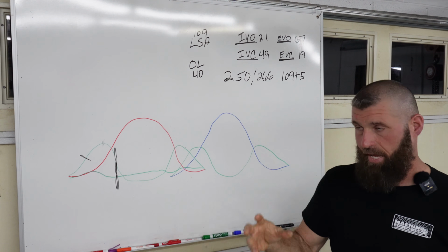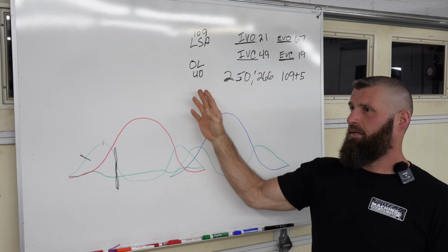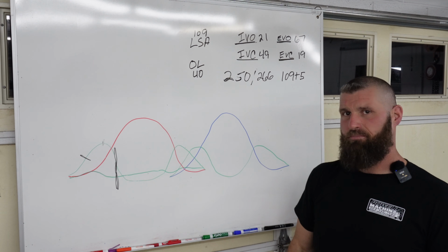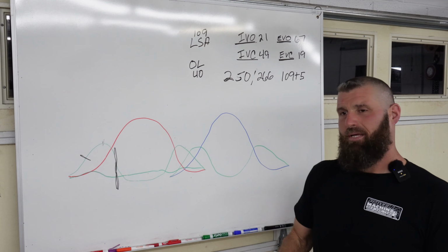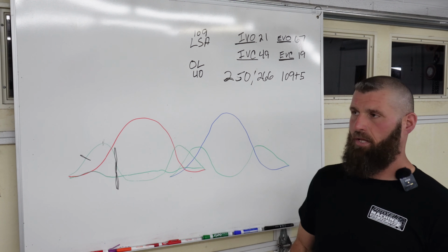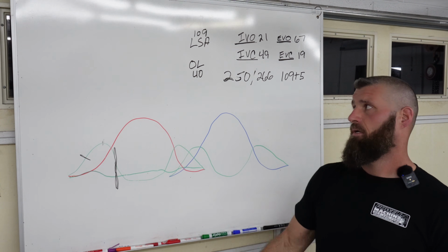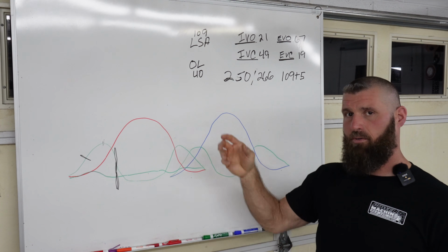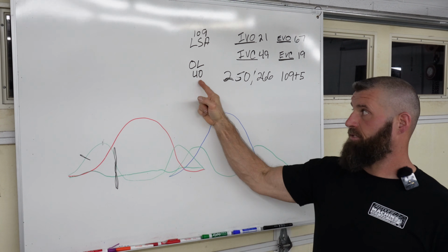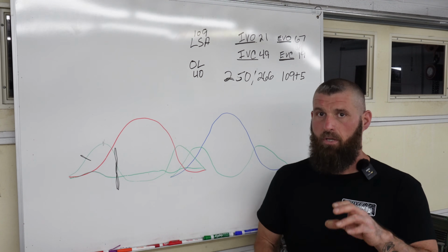So that's kind of that deal. And, you know, maybe overlap is super subjective. I mean, there's so many variables. Some cylinder heads have a lot of cross flow. You got to be careful with overlap. Some cylinder heads don't have a lot of cross flow. Overlap's not quite as important. It can help, you know, with scavenging and cylinder filling. A lot of this number is directly correlated to header tuning.